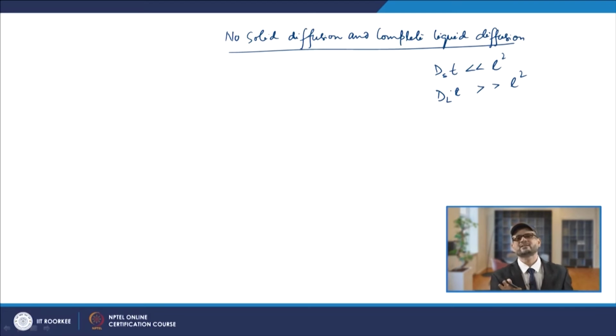In fact, the concentration of solute in the liquid will go on increasing, and since the solid has to come out from this liquid only, the solid which is formed later on will also have its concentration go on increasing.